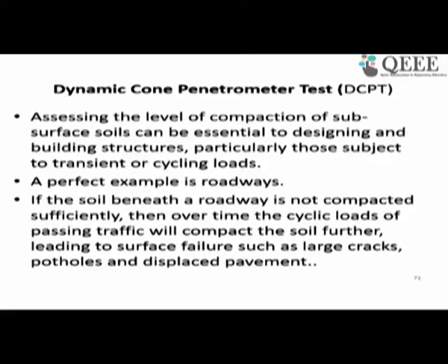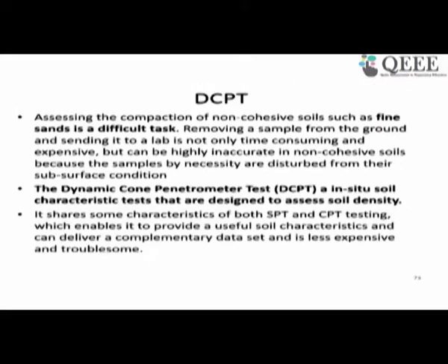Now, assessing the compaction of non-cohesive soils, for example fine sands, is really a difficult task. It is not possible to get an undisturbed sample of non-cohesive soils. So in situ tests are advisable, as sending samples to a lab will be really difficult in the case of sandy soil. The dynamic cone penetration test in such a situation will be very helpful to give you the value which is desired for the design.